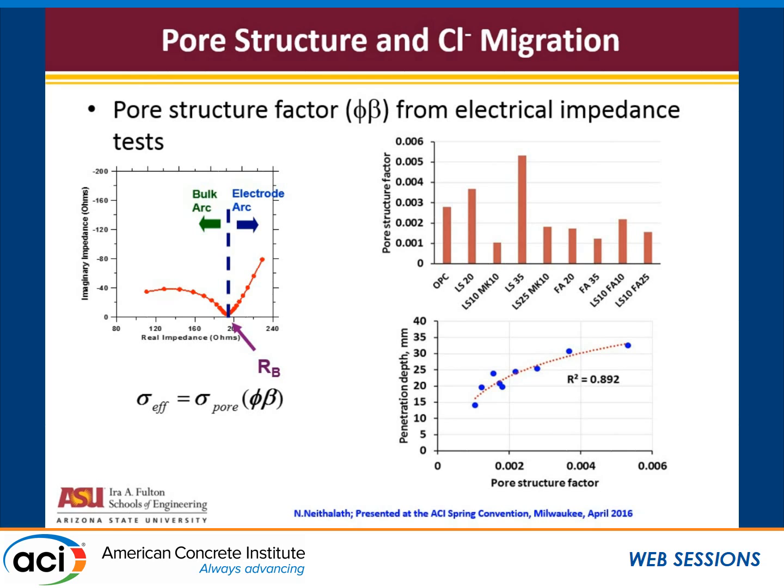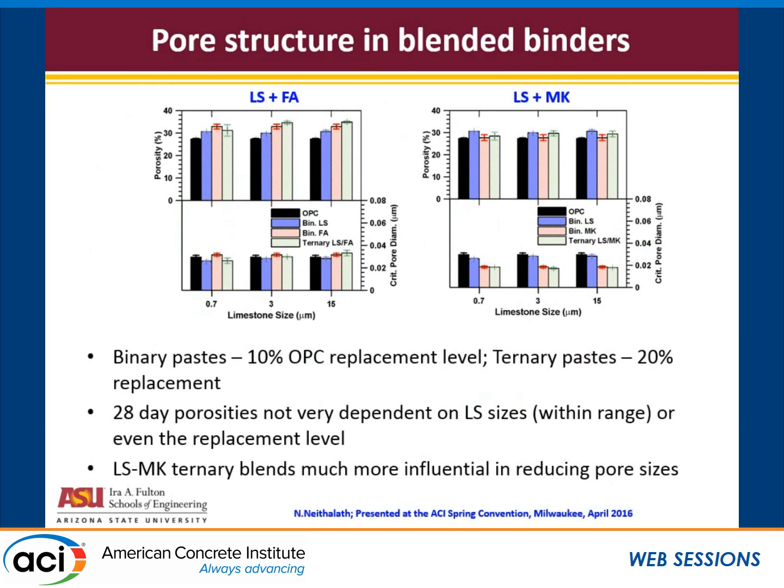Again saying that you can have a simple electrical test to find what the pore structure is and relate that pretty well to how deep the chloride ions go through. I have a couple of other things on pore structure and blended mixes. This is just to give you the idea that we have always focused on porosity when we talk about concretes. Like we say, reduce the porosity, reduce the porosity, reduce the porosity.